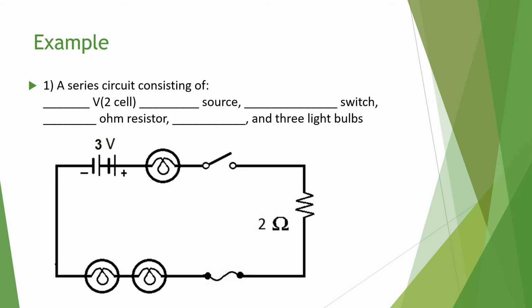If you were to draw a circuit, okay, this would be the energy source, positive, negative. When measuring the voltage, you connect the voltmeter across. So you add it in like this. Whereas when you are connecting an ammeter, you put it right in the circuit. So if this was the battery, then the ammeter would be added directly inside.